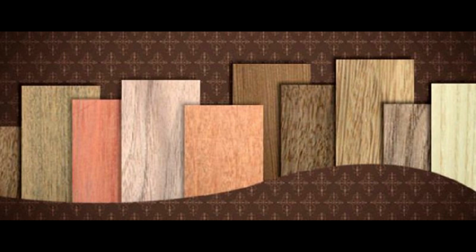And flexible plywood is designed for making curved parts, a practice which dates back to the 1850s in furniture manufacturing. At 9.5 mm thick, mahogany 3-ply wiggle board or bendy board comes in 4 by 8 feet sheets with a very thin cross grain central ply and two thicker exterior plies, either long grain on the sheet or cross grain.